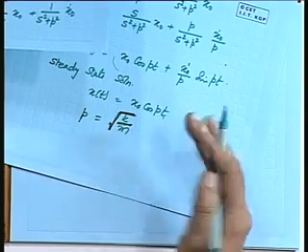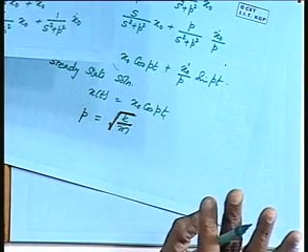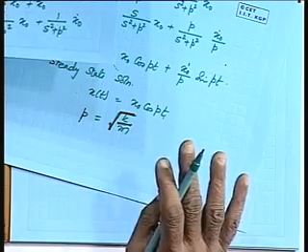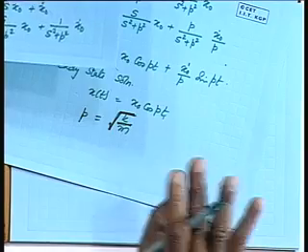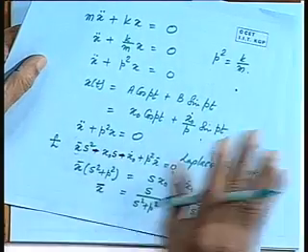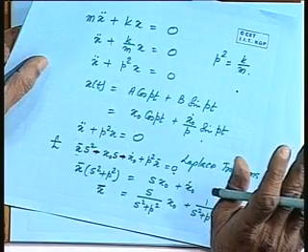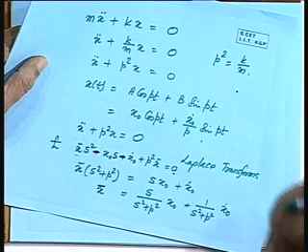Now, we are basically not interested in increasing the structural weight. So, we will not touch the material. What we will do? We will try to change the stiffness. How the stiffness can be changed? Stiffness can be changed because we are using in ship structures stiffened plates mostly. So, the disposition of the weight. So, you play around with the size of the stiffener, the spacing of the stiffener, the positioning of the stiffener etc. That will change the vibration property of the structure. It's okay. I think with this I have introduced what is vibration.